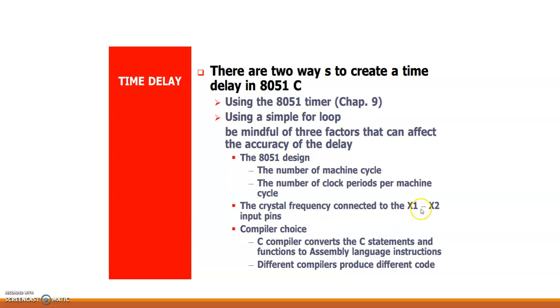We know that the 8051 microcontroller has the XTAL1 and XTAL2 input pins. A crystal oscillator will be connected to these pins, and the frequency of this crystal oscillator determines the clock period of the microcontroller. And another factor is the compiler choice.